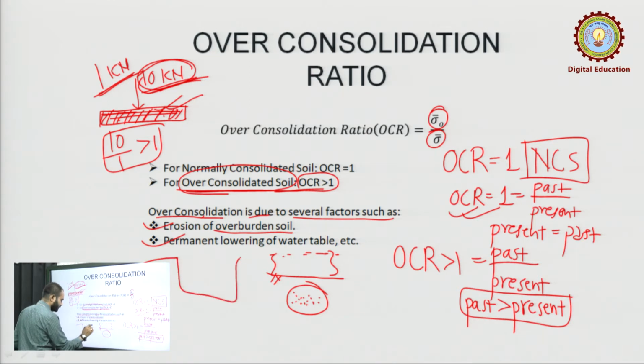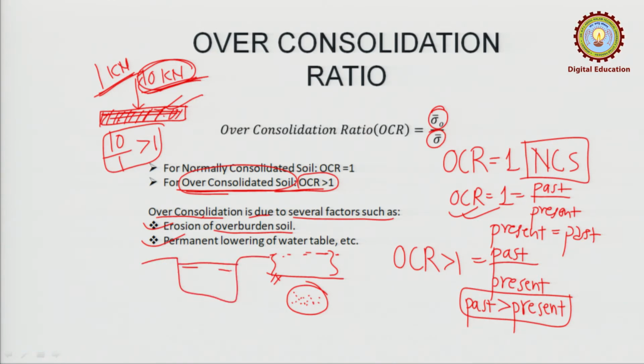Similarly, in case of a water body, say if a water body is filled like this, first of all water will be also here, pore pressure will be exerted and all. So it has a different pressure condition. Now if water reduces here, water gets lowered, then this part gets freed, this much part gets freed. So this part will remain as over consolidated, and this will be again under the normally consolidated only. Okay. So, this was it.